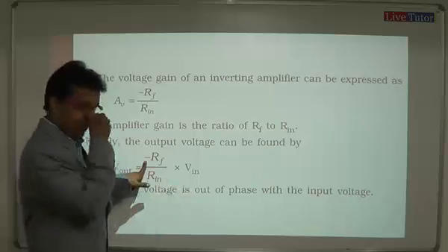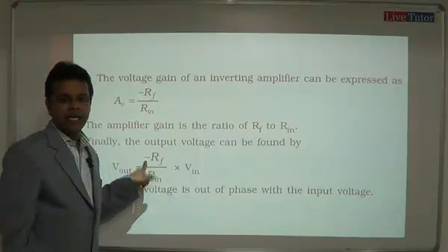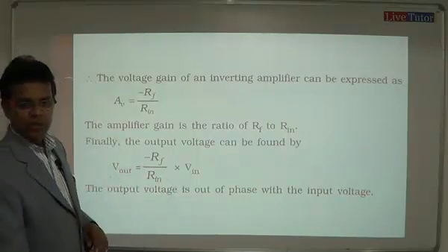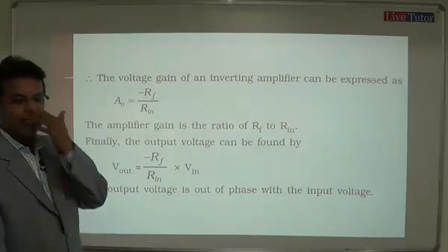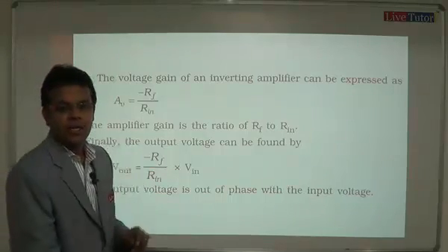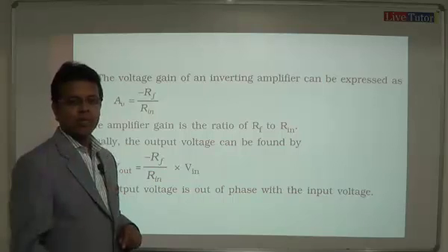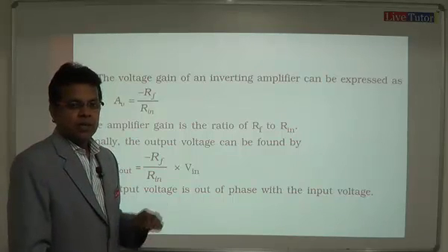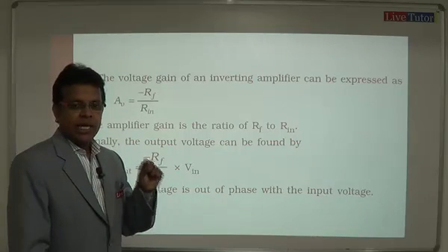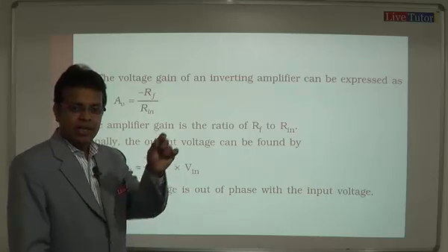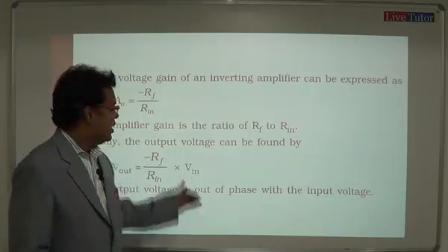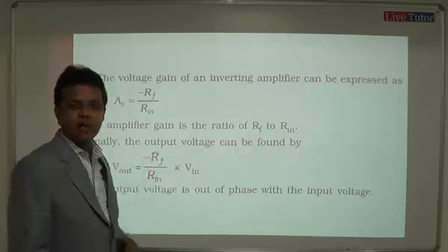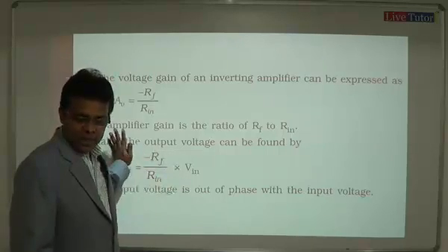Inverting means what are we doing? You have to remember that it is giving us a negative sign. When we give a positive voltage, it will give us a negative sign. When you measure, you will see on the digital meter that it shows the negative sign. You remember? So where do we start? IN is equal to IF. From that you have to find out the derivation. Then the final answer can be found easily.